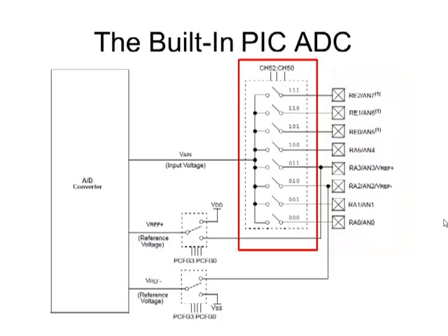There's something inside the A to D converter called a control register. There are a couple of control or configuration registers, and these tell us how this ADC is actually being used and what configuration it's being used. There are 3 bits that are called the channel select bits. So these 3 bits tell you which channel you are looking at. So if we were looking at analog input 0, I would write 0, 0, 0 to those 3 bits. If I wanted to look at analog input 7, I would write 1, 1, 1 to those 3 bits. We'll take a look at that whole register in a couple of minutes.